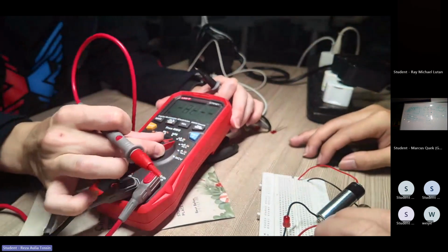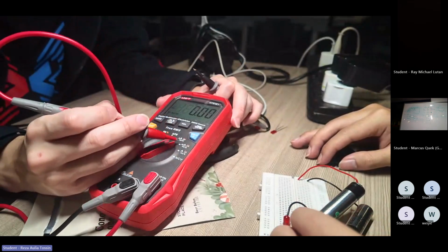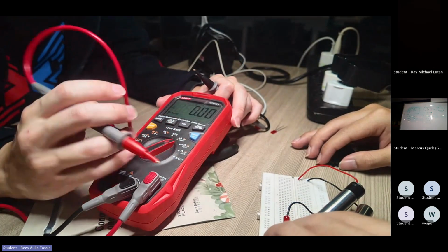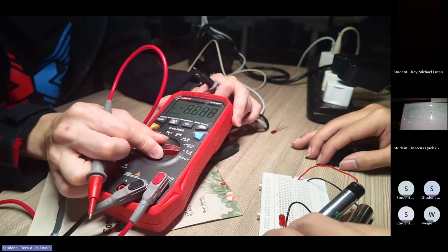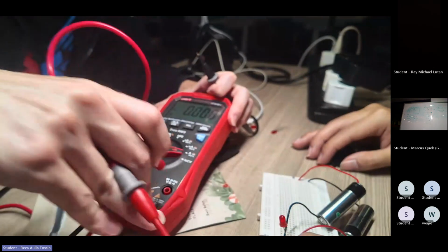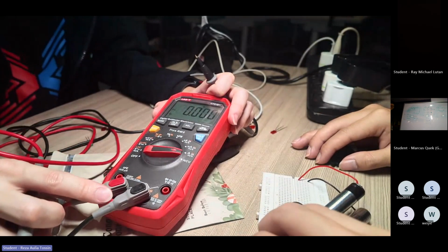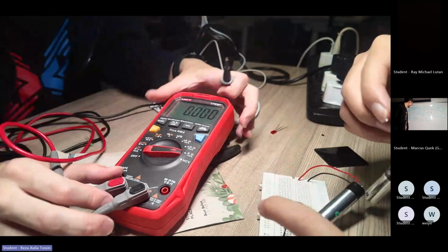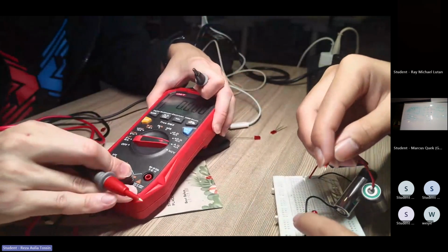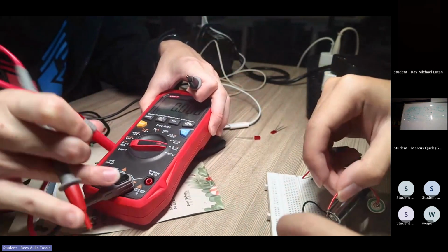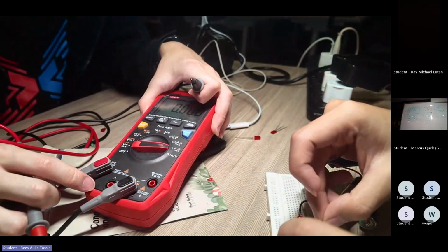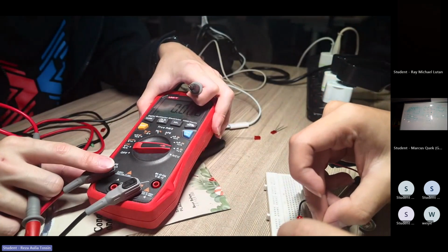Okay. This is amp mode, so measuring microamps, milliamps, or amps. You need to set to the correct range of sensitivity, and then choose accordingly whether you want amps or milliamps or microamps. So let's say I want to measure amps, then I'll go here and I'm measuring some huge current. It'll be less sensitive than if I measure milliamps or microamps. So when I do this, this is in current mode.